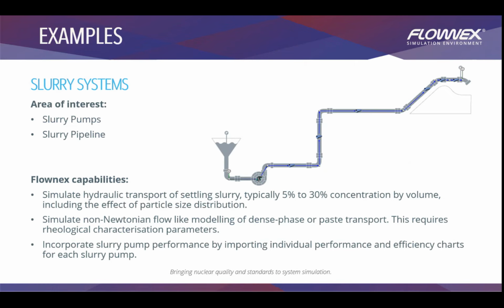Then we have some slurry networks. It's not related to water, but slurry networks do contain water, so we'll need water to move most of the particles. That's where slurry will also be part of this water distribution system in some sense, where we'll have to provide water to the particles and move them as one. So you will be able to do slurry simulations in Flownex as well. The points of interest will be slurry pumps and slurry pipelines, and you can do hydraulic transport of slurry, typically 5% to 30% concentration by volume.